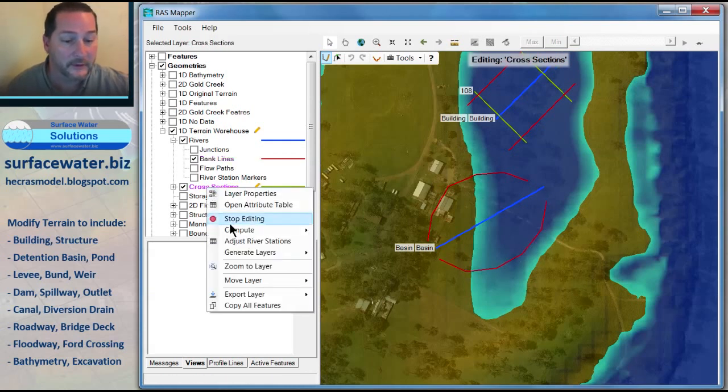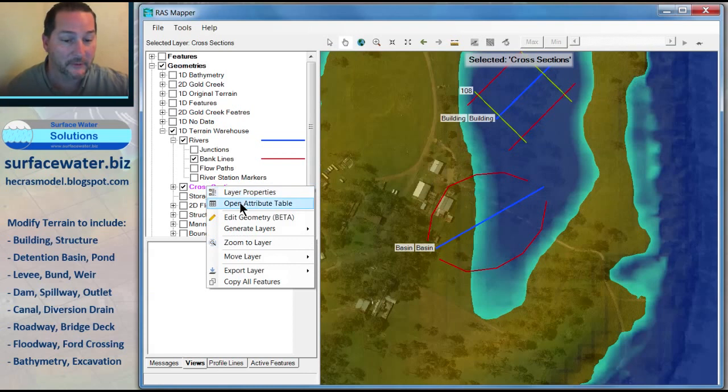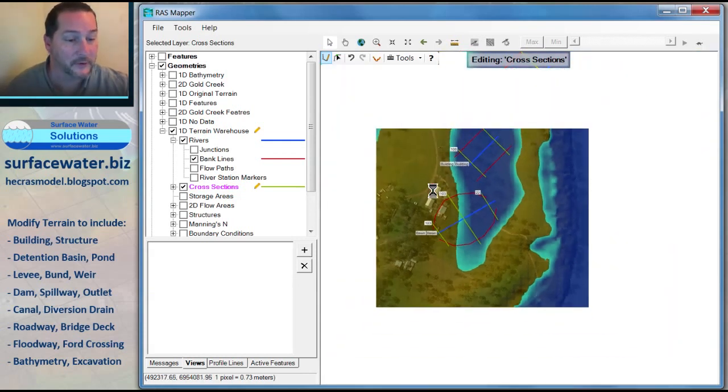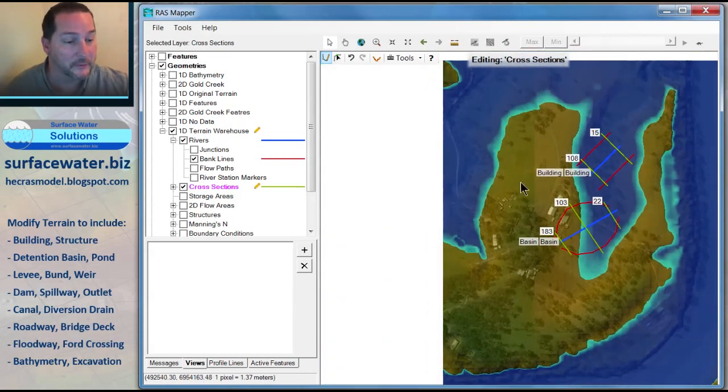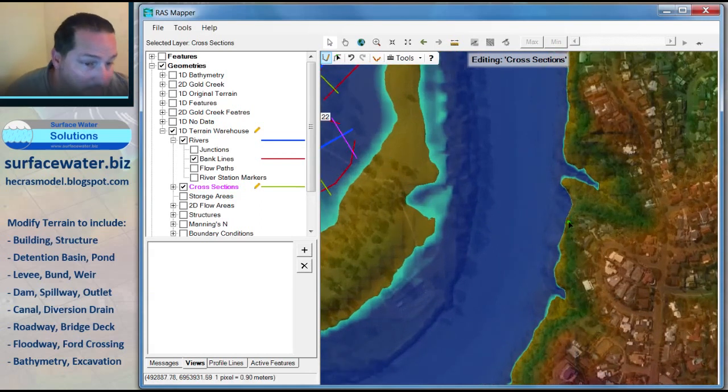The cross sections themselves, sometimes I like to daylight them on the ends and leave those ones at the ground elevation, tapering out to my next section. We'll show you how that works when I get into the cross-sectional data. I'm just going to define this one with just 3 cross sections for now. And again, make sure they cross once and only once. You will see missing reach if you missed this with one of your sections, and you won't see a value here. So you've got to make sure you see values for every one of these when you're done drawing them. That shows you that you've got what you need here. We do need access to this thing, so let's put in a roadway as well.